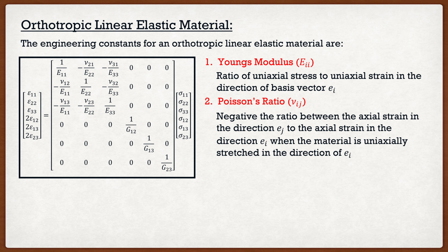You guys have dealt with Poisson's ratio before, so most of you know what it is, but for those who don't, it's basically this. For civil engineering materials, and I want to make it clear, civil engineering materials, because there are cases where this doesn't really hold, it's basically this. If I were to compress a box, we expect that once I compress that box vertically, it is going to expand horizontally. And this is why I say sometimes, because there are materials that when you compress them, they also compress in the other direction, and vice versa. But for the most part, for civil engineering materials, concrete, steel, if we compress them, they're going to start to expand horizontally. That's basically what the Poisson's ratio takes into account.